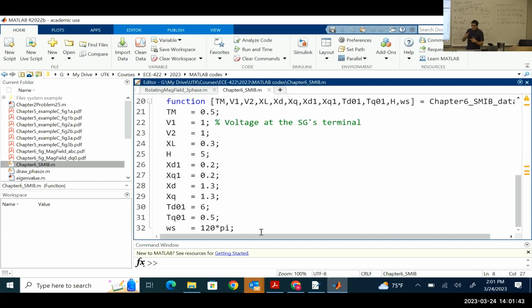And then also we will have some dynamics related to the field winding as well, right? So these time constants are related to the field winding dynamics and also to the 1Q dampers. We're ignoring the 1D, 2D, and 2Q dampers. Those are going to be assumed very fast, and they are going to respond instantaneously. Okay? Any other question?